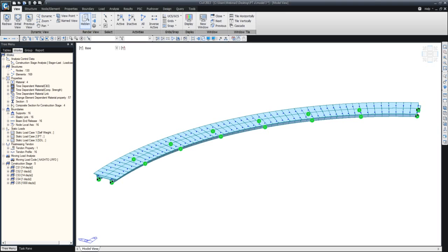There's a very good point made out here. When you post tension, are the temporary supports restraining any vertical movement upwards or creating secondary effects? Yes, that's a very good effect. If our members are restrained by the temporary supports, and then the post tensioning is done, there will definitely be secondary effects in the structure, because it is at the end an indeterminate structure.